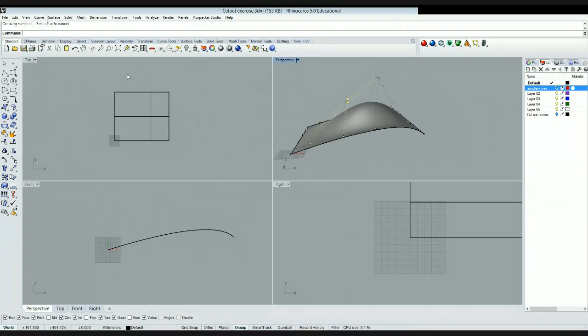And now, if you notice in the initial image, my surface is not rectangular in plan, but it has a specific shape. So now I'm gonna draw this shape, and we're gonna trim the surface that we have already designed. So I'm going to create from curves a rectangle from corner to corner. I'm gonna start from 0, 0, 0, and I'm gonna end at the diagonal corner of my surface. So now this way I have the footprint of my surface on the XY plane.